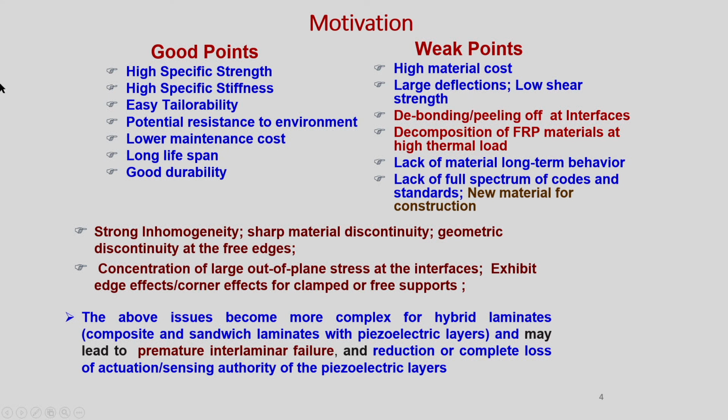The weak points are high material cost, and debonding and peel off taking place at the interfaces. That is the most important reason why we do not allow complete application in different fields. Then there is the lack of knowledge about the long term behavior, like fatigue and fracture, and how it will behave over long durations.